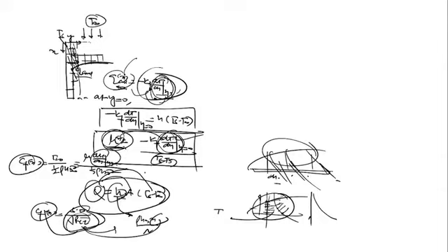What should I do? To find the heat transfer coefficient expression, we must know the temperature distribution, and to find the temperature distribution, what should I write? I should write the momentum balance and energy balance. I will show you each and everything through examples. So by writing the momentum balance and energy balance, I can find the temperature distribution. So again, momentum balance is compulsory. Without momentum balance, you can't solve the energy balance. Similarly, in mass transfer, without momentum balance, you can't solve the component balance. Clear? That's why the role of fluid mechanics is important in the study of convective heat transfer. That's why every time I'm saying how much importance fluid flow or flow profile has in convection heat transfer. Is this clear?